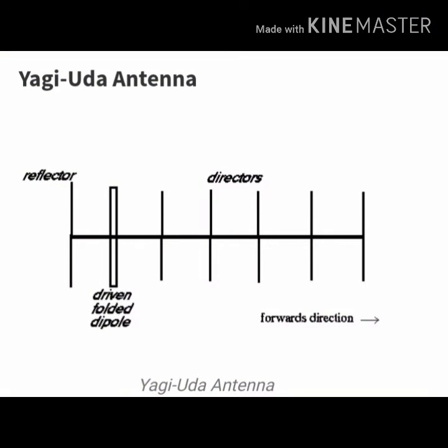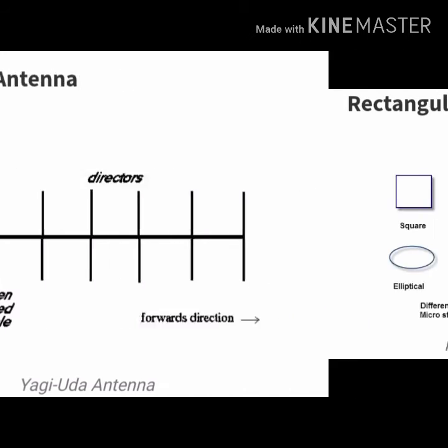Yagi-Uda antenna. Another antenna that makes use of passive elements is the Yagi-Uda antenna. This type of antenna is inexpensive and effective. It can be constructed with one or more reflector elements and one or more director elements. Yagi antennas can be made by using an antenna with one reflector, a driven folded dipole active element, and directors, mounted for horizontal polarization in the forward direction.